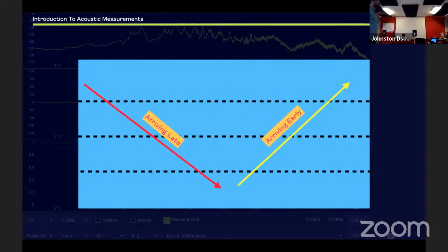It's just going to be a flat line. But the moment the measurement signal starts getting delayed, there's going to be a trace that is created and this trace will start pointing downwards. So when the trace is pointing downwards, it means that the incoming signal, the measured signal, is getting delayed by that many degrees and you'll be able to read that delay.